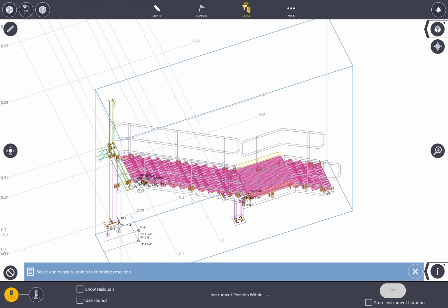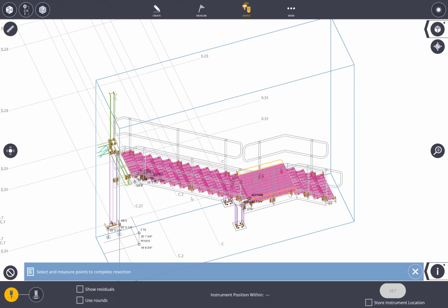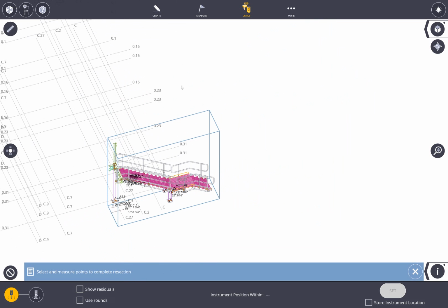So if we wanted to set this assembly up in the shop for fabrication, we can come in here, and there's a couple different modes that we're showing right now in the emulator. So we have a setup anywhere. We could set the total station up on the project, maybe out here in the dirt. We could shoot 2 of the grid intersections, and it would triangulate the position of the robotic total station, and we could lay out the rest of the project from that location on site.